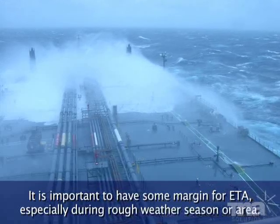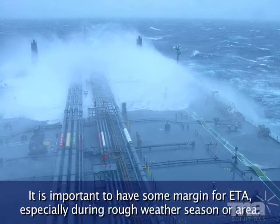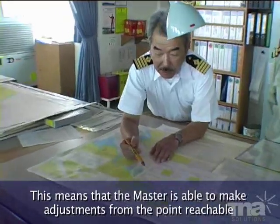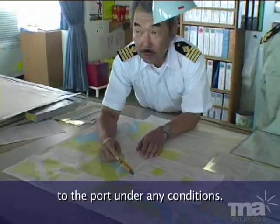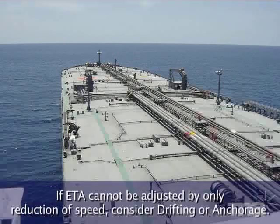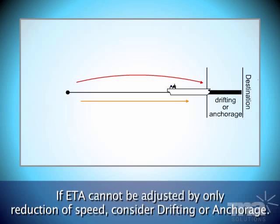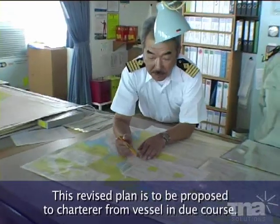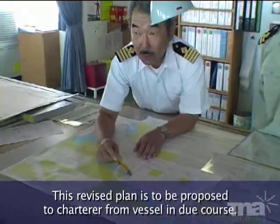It's important to have some margin for ETA, especially during rough weather season or area. This means that the master is able to make adjustments from the point reachable to the port under any conditions. If ETA cannot be adjusted by only reduction of speed, consider drifting or anchorage. This revised plan is to be proposed to charterer from vessel in due course.